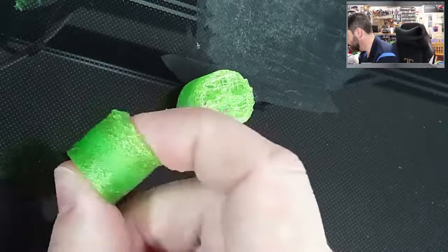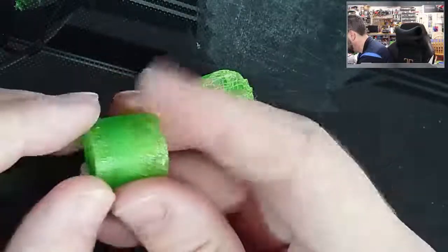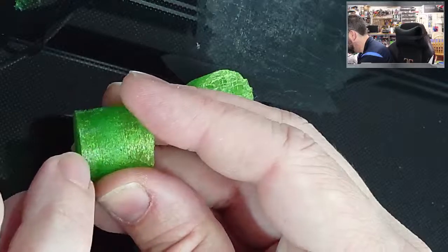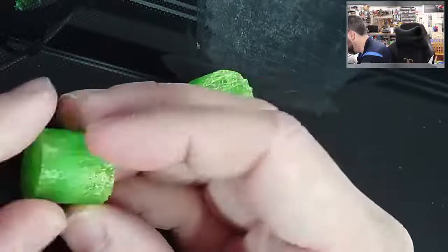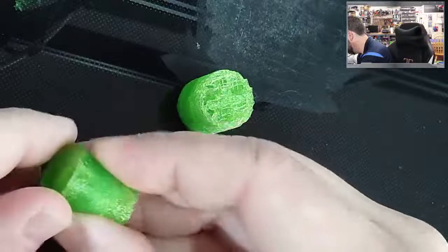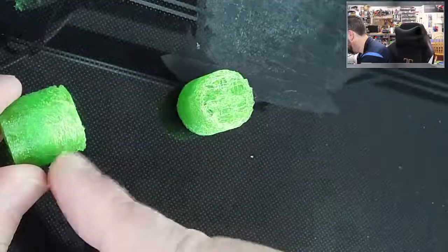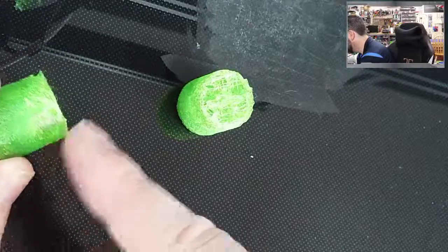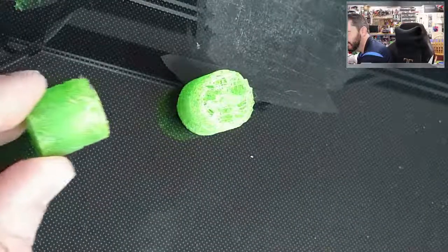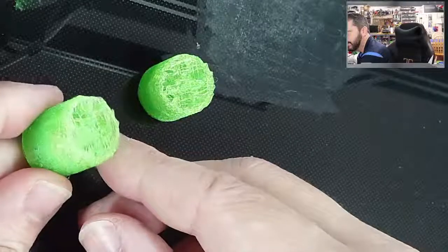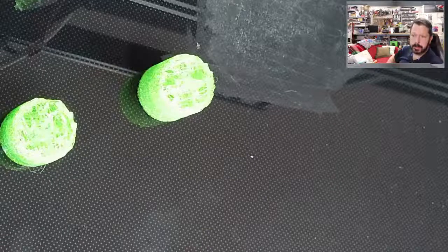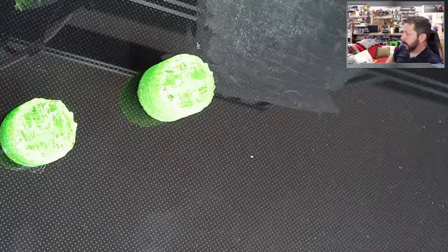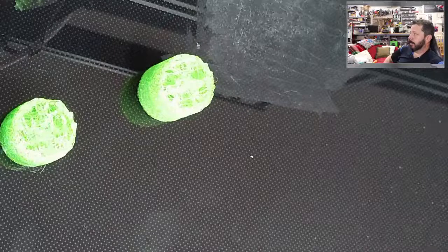Then I put the filament in the dryer for a couple of hours, and it started printing better. Like this first part here was okay. It's not horrible. And then I raised the temperature and it got a little worse, maybe. It's bonded better, but I think it's actually a worse print. And then this usually looks like there's some heat creep, like the nozzle's getting clogged up here, where it gets really stringy up there. So I might try printing again. First I might try leaving the filament in the dryer longer, because I don't know how old that filament is.